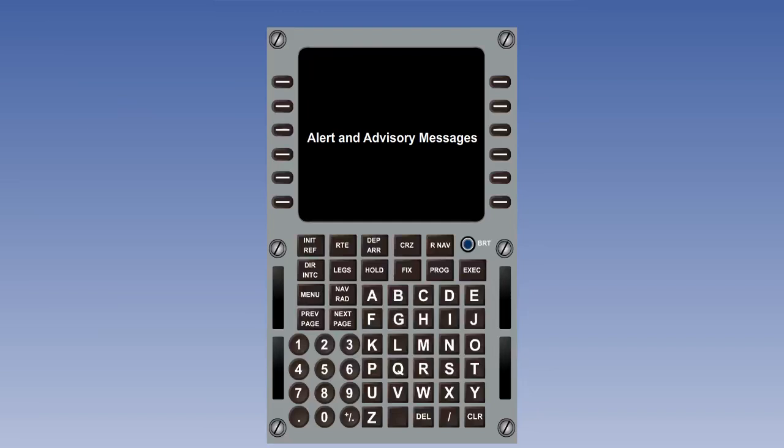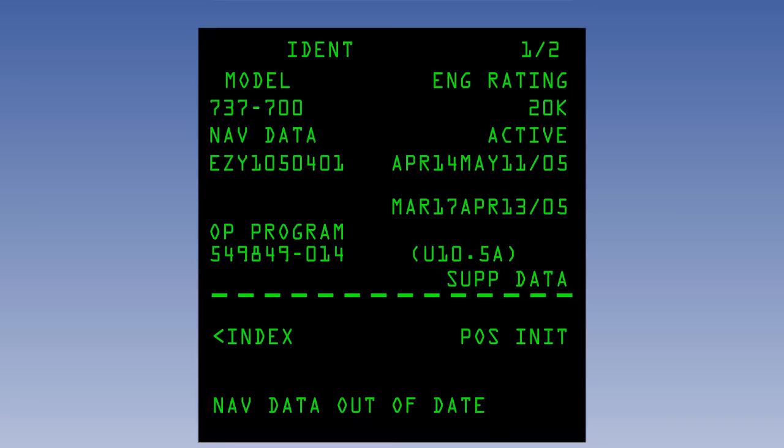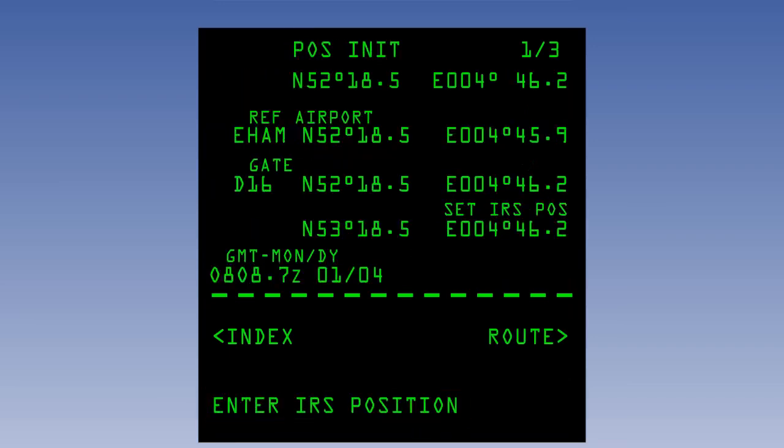However, the scratch pad also has a second use. The computer is programmed to pass relevant information to the pilot should it be necessary. These are called alert or advisory messages. Alert messages have the highest priority, and they identify a condition which must be acknowledged and corrected by the crew before further FMC guided flight is advisable, or even possible in some cases. Advisory messages have lower priority and inform the crew of the CDU entry errors or system status.